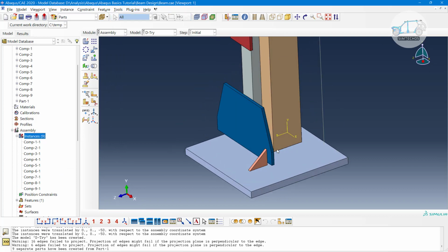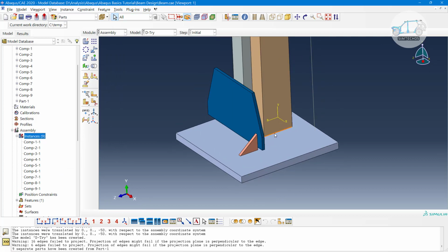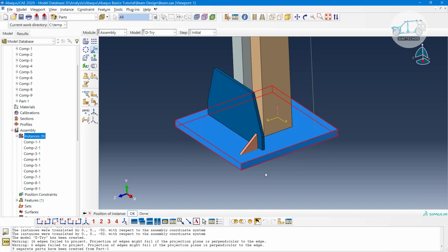So, as we know, this plane I created at the distance of 50. So, very quickly you can go with these options. Okay, I do not recommend utilizing these options. Only in this specific case you have to utilize them, otherwise use the translate and rotate options, because the software will create the constraints between the geometry and then moving those components with respect to the constraint will be difficult. Okay. So just move this component in y direction. Let's say this is the 50. Fine.